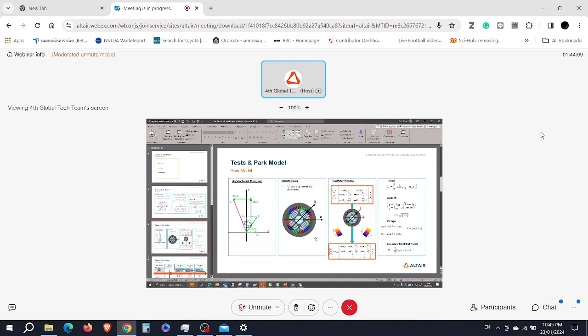And finite element computation is used in magnetostatic in order to extract phi A, phi B, phi C. Then we are going to supply all three phases with IA, IB, and IC, vary the current, vary the position, and recover the magnetic flux on phase A, phase B, phase C.